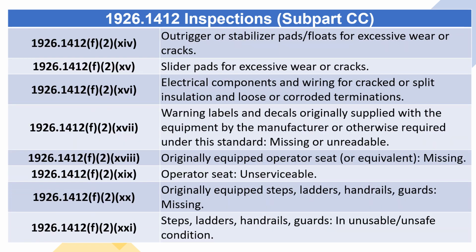Outrigger or stabilizer pads/floats for excessive wear or cracks. Slider pads for excessive wear or cracks. Electrical components and wiring for cracked or split insulation and loose or corroded terminations.